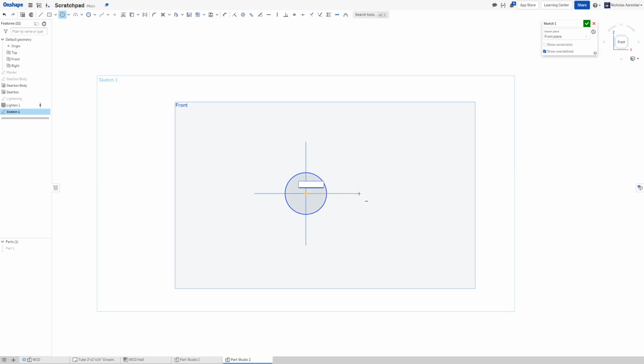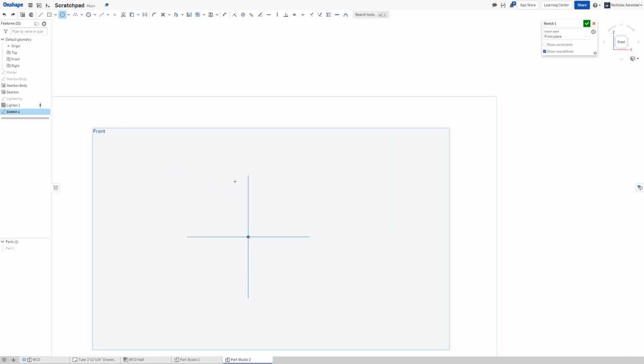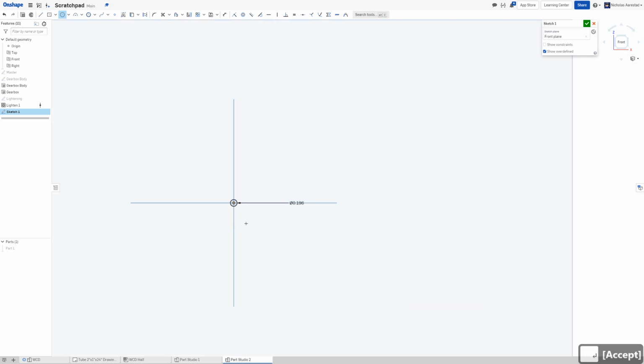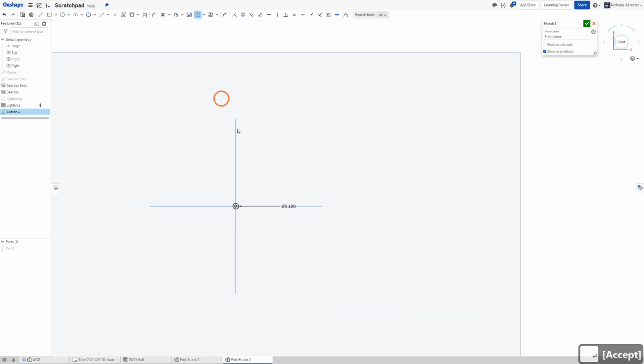So let's say I am back in the dark ages without the tube feature script, and I want to create a tube that's at an angle. That might not be the best place to start. So let's just first introduce the linear pattern. So this to be 0.196 hole. That's a number 10 size hole, and I would just want a linear pattern of that.